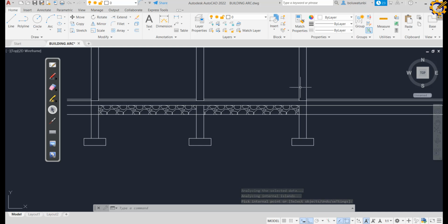Now, if you've been to a standard construction site, so some of you are going to go for IT and you will actually witness what I'm trying to explain now. So for a standard construction site, after the site preparation, you've cleared the bush, the next thing is setting out. After setting out, the next thing is what? Excavation. After excavation, the next thing is what? Foundation. So after erecting the foundation, it is expected that they will do the ground floor, the flooring.